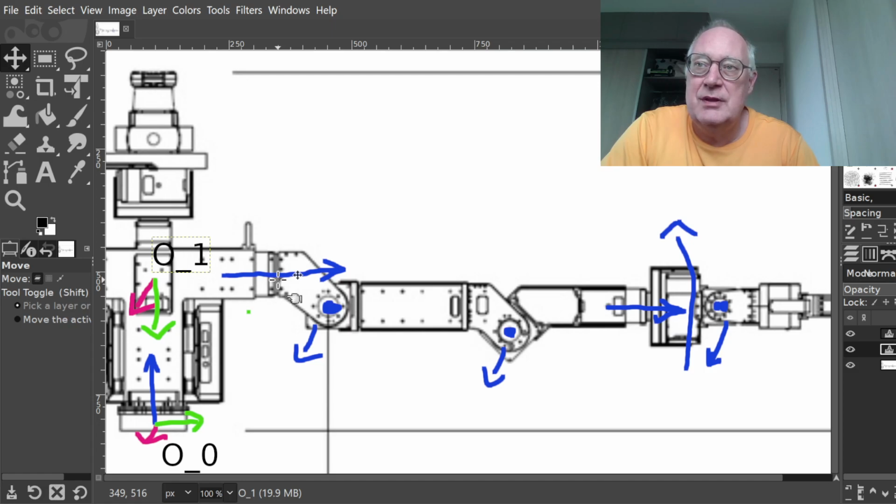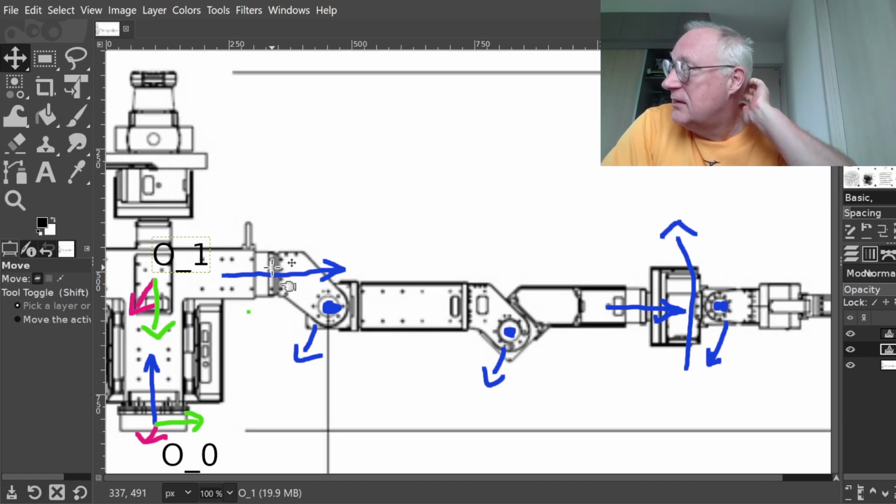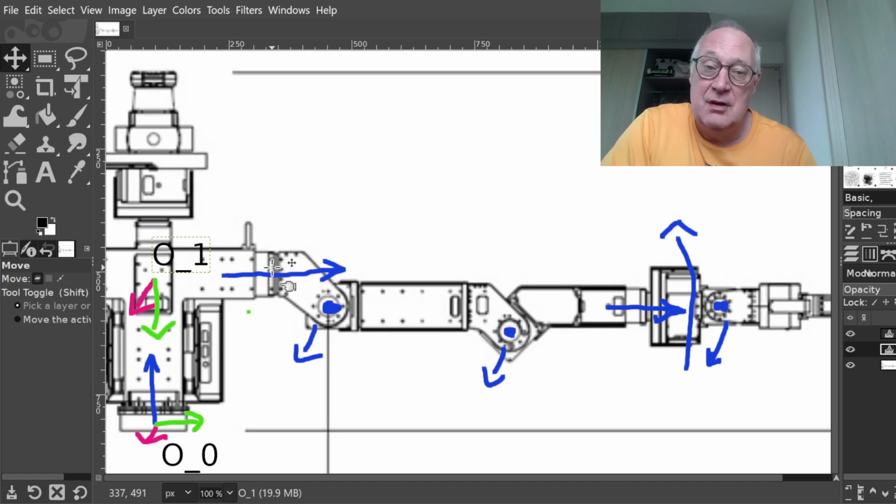closely matched to where the position of the joints are, so that when I read off the coordinates, I get an idea of what the control is that the servo motor is currently sending, for example. That's why I also rotate around the z-axis an extra step often, in order to align the coordinate system so that the joint angle 0 really means that it's in the home position for the robot.